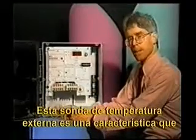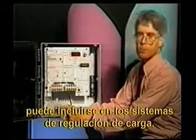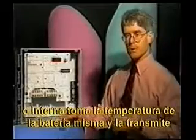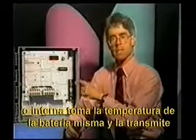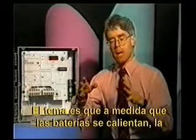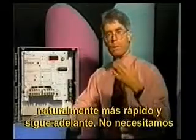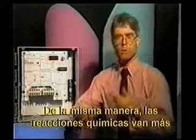One feature that might be included in charge regulating systems is a probe like this, an external temperature probe. This is for what we call temperature compensation. The external probe or internal probe measures the temperature of the battery itself and transmits that to the electronic controls in the charge regulator. The point is that as batteries get hot, the chemical reaction going on inside the battery is naturally going faster and further. We don't need to charge the batteries as much when they get hot. The contrast is true as well.